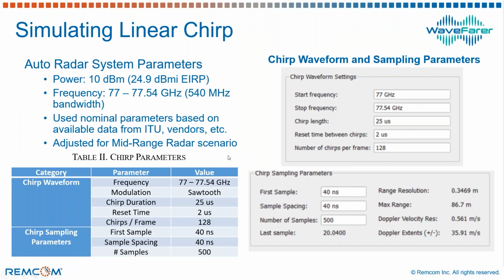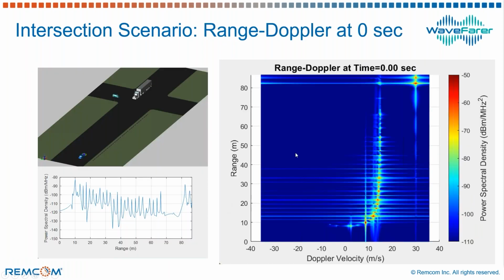Returning to our chirp and our Doppler calculations, now that we have the simulation performed, that script is going to kick off a series of simulations that capture all the information we need for those 6 snapshots. In total, there'll be results from 12 different simulations capturing those 6 frames. Our first frame was at 0 seconds into the simulation. This is the relative position of where everything was. Our Doppler calculation produces a plot of the Doppler versus time. We can see interactions with guardrails, the truck, and the car over here in the distance.